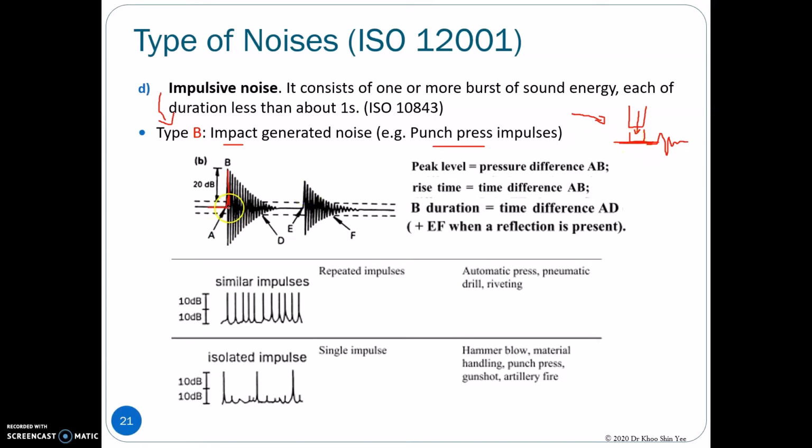Therefore, you see there is an oscillating, decaying response afterwards. If the removal of the punch hammer is not fast enough, then refraction towards the punch hammer will happen, and in this case, you obtain a second impulsive due to the refraction.